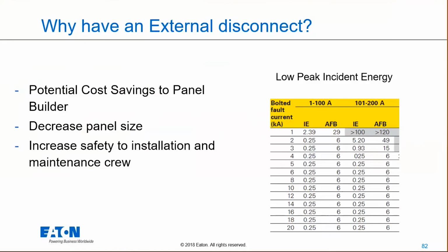Because you've now turned it off, there's nothing even on the line side of that panel. So there are a couple of really good reasons. One, if you do have to work on it live for whatever reason, you're going to have the benefit of a very good current limiting fuse above it, especially if it's a Class J fuse, which is very common. And two, you're going to limit your exposure if you do happen to put it inside the cabinet. So there are very good reasons to put it external to the cabinet. I strongly encourage you to do so.